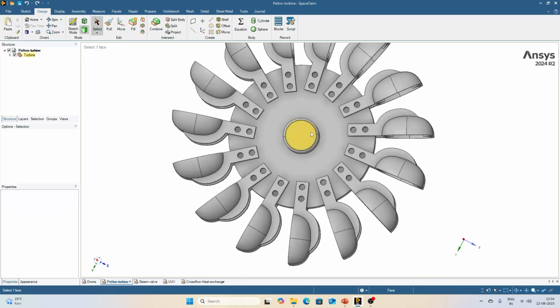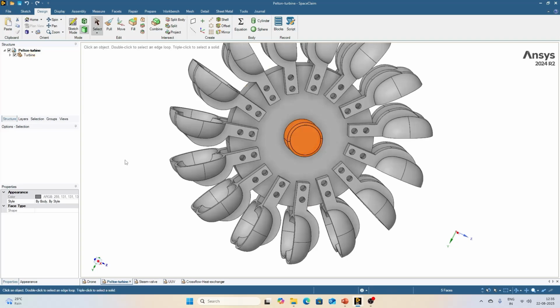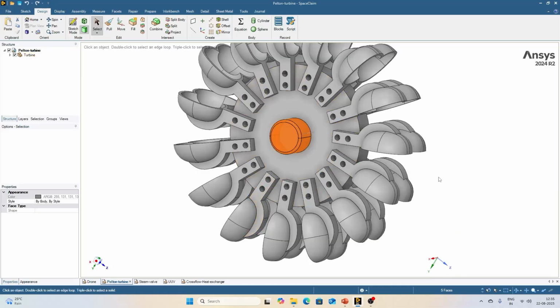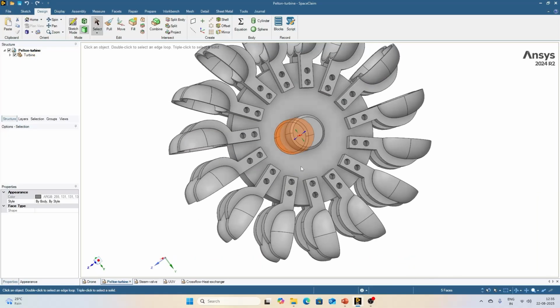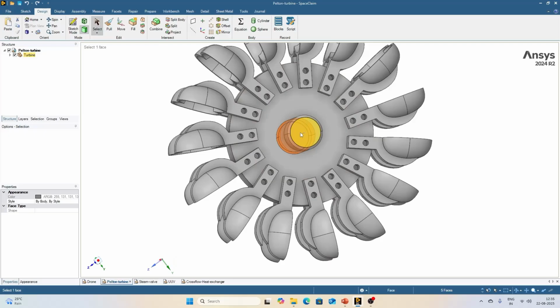Let me try this option for this shaft. So left click and go around this object to create a free-form shape. You can see the shaft is now selected. The information is updated over here. You will notice one thing here, that the shaft behind the view was not selected. It's because of the default selection filters.